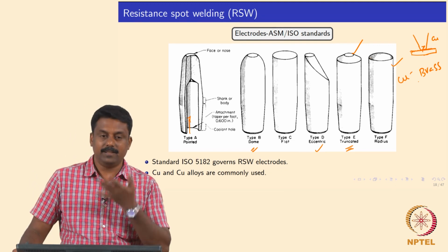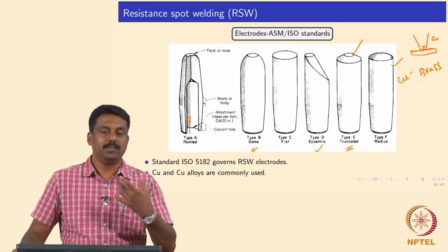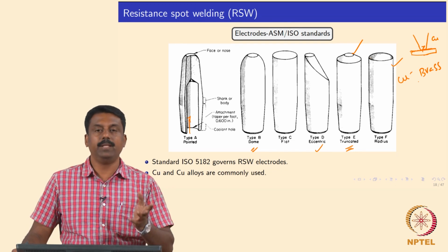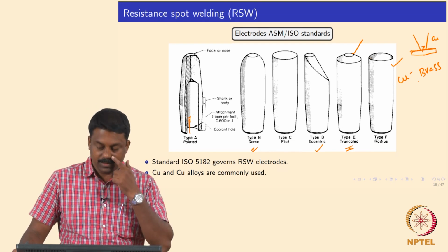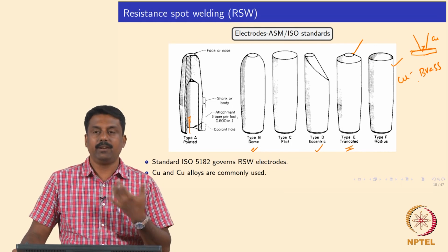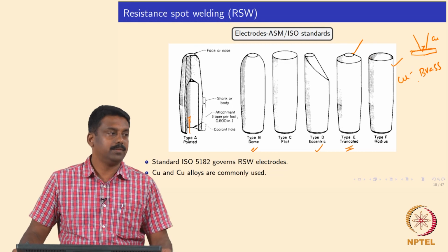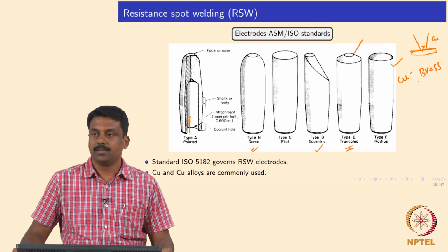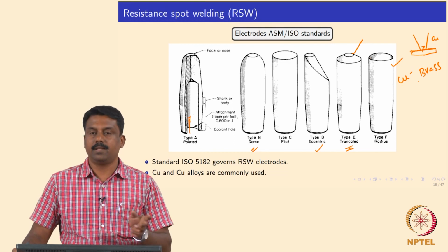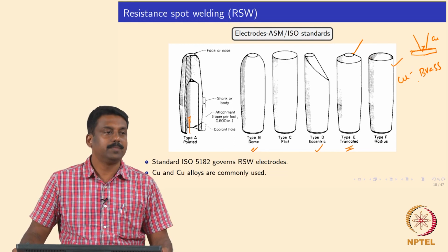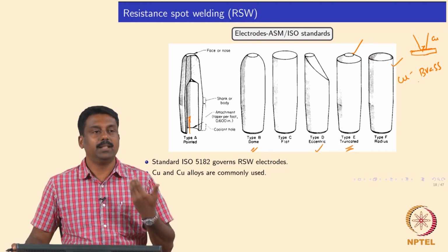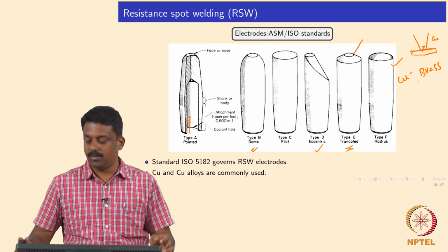Obviously these oxides can improve the electrical conductivity and the mechanical properties of these electrodes, okay. So people thought about replacing the conventional copper with rare earth added copper electrodes, or even entirely replacing copper with other super alloys, for example cobalt chrome,